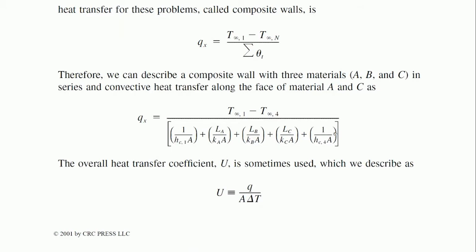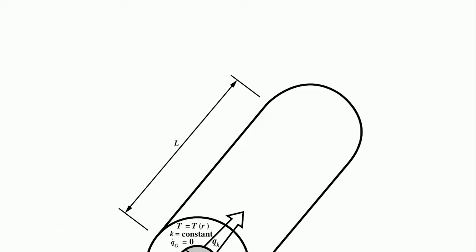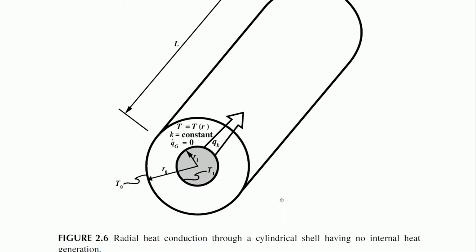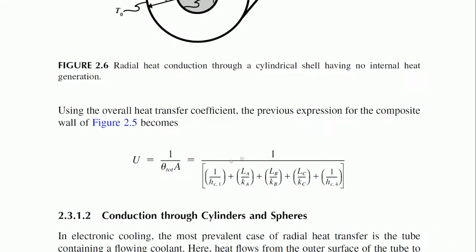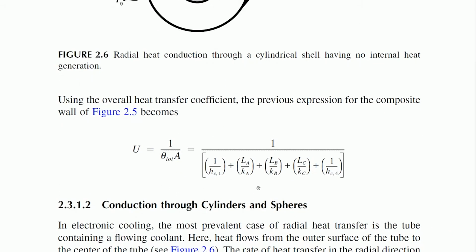The advantage of a resistive circuit like this is all the resistances can be added easily, just as you would do. So, resistance 1, 2, 3, then you have a temperature difference, and in the end we have a beautiful thing. We have the overall heat transfer coefficient, which, given an amount of power and given an amount of area, we can directly compute the effective circuit. You have seen this, no? This is what a commercial heat sink manufacturer will be giving. This is what I have spoken to you also earlier.